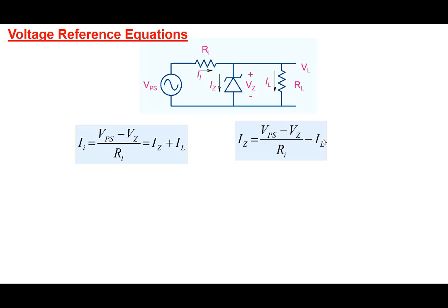And so now the issue in using a Zener diode is we have to make sure that the Zener diode is operating in the Zener mode, in that steep IV characteristic, or in the breakdown mode. And further, we have to make sure that the current through the Zener diode doesn't exceed its maximum current rating, or the power dissipation in the Zener diode doesn't become excessive. So let's calculate what IZ max is here.